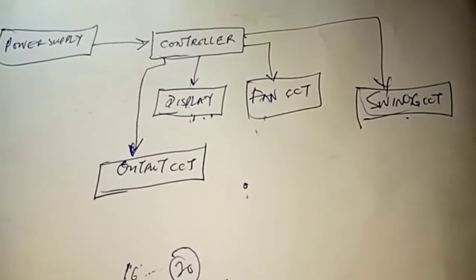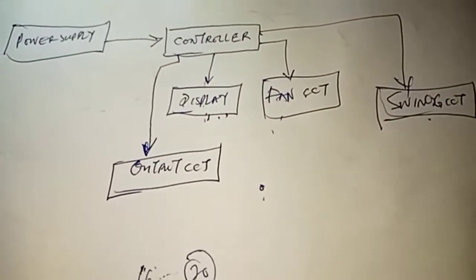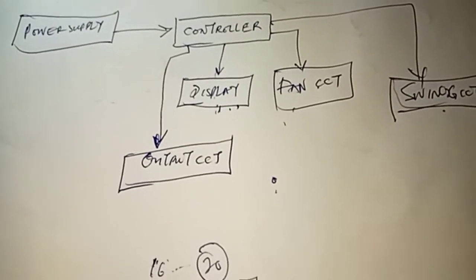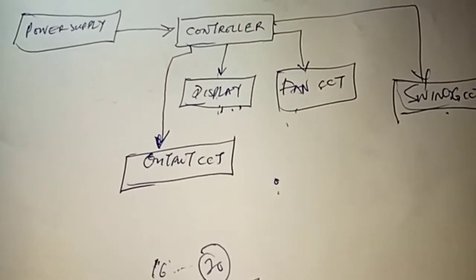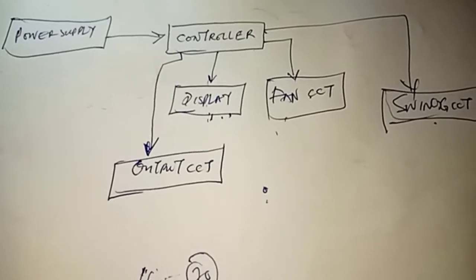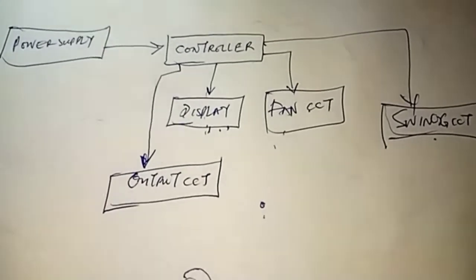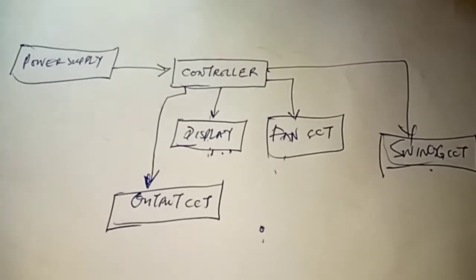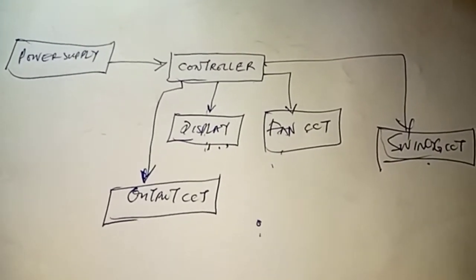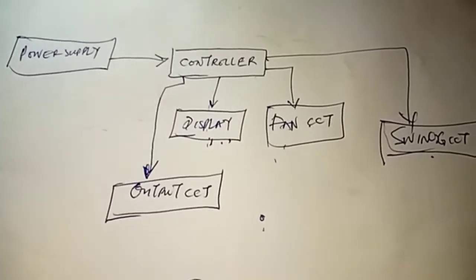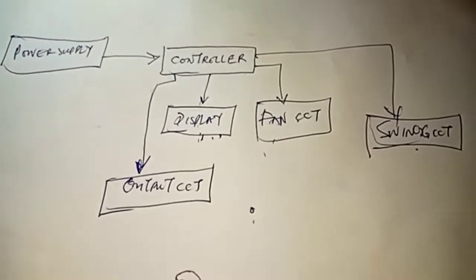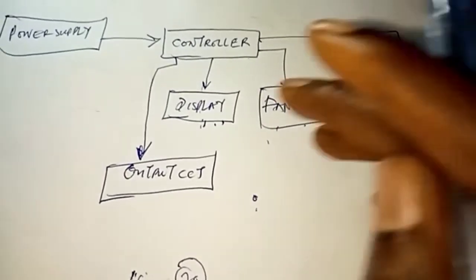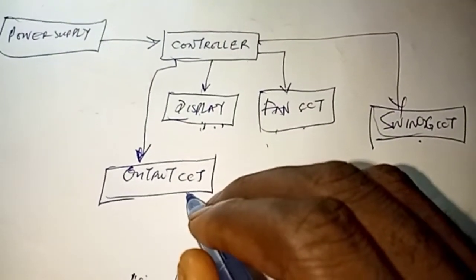Now, those are ways to protect your system, because you must reason a way out to protect it. One basic thing is that you are protecting the compressor from damage. So that comes with adding error codes, or letting this circuit design detect errors. Majority of them, if it detects that the fan is not working, it will not send to the output.